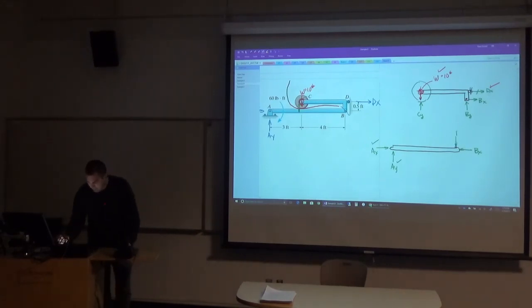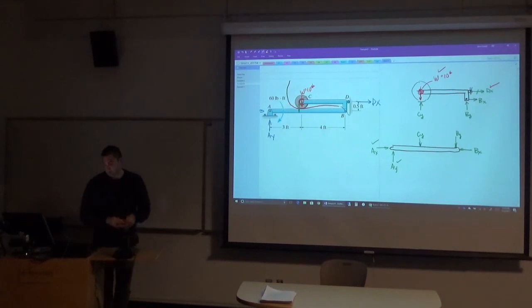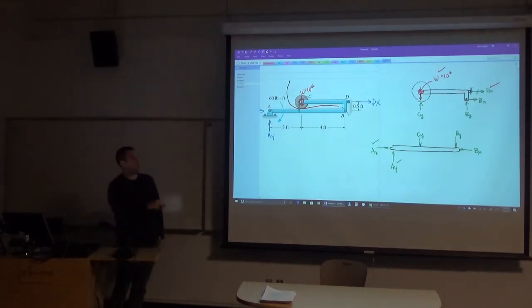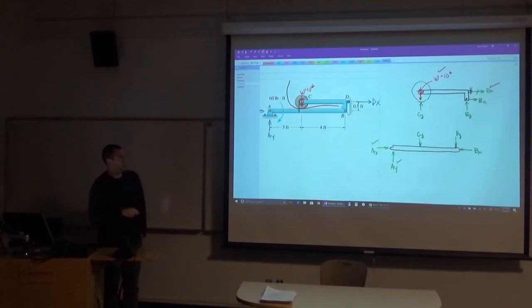And so then BY, I'll show opposite of what I did on the upper free body diagram. And the same thing with CY, I will draw that opposite of what I did for the top free body diagram. The only reason I'm doing that is that, if I use either free body diagram, as long as I show these forces along the interface equal and opposite, I'll get the same exact answer, same exact sign, regardless of which one I use.